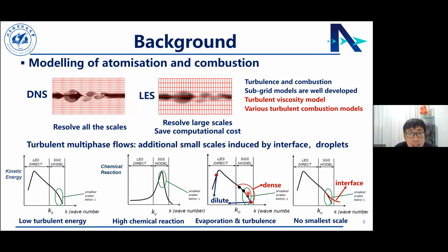Let's see the current numerical methods for interface flows. We know level set and diffuse interface. But currently, as I know, for the LES application to spray atomization, the VOF method is at the front, mainly because of its intrinsic conservation of mass and its numerical stability.